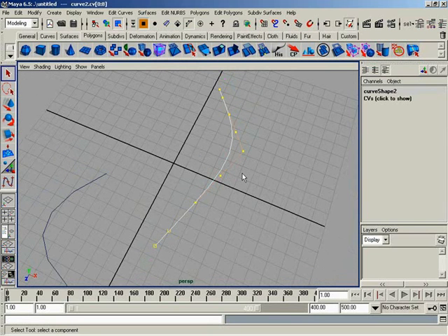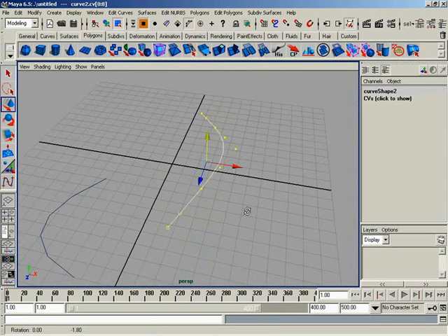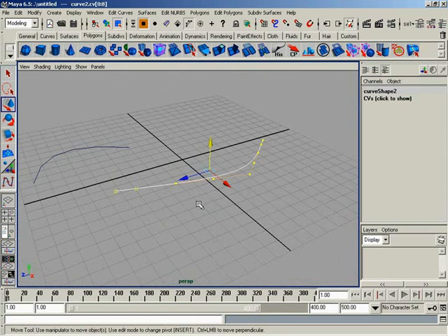Holes are very important when modeling, and you need to grab a consecutive row of CVs. You can simply turn on holes, grab that hole, and you have all of the CVs. Of course, I still have the ability to go in and grab the CVs on an individual basis. A hole is not something that you can manipulate per se. Again, once you select a hole, you're really doing nothing more than selecting all of the CVs. Just grab my move tool, start moving these around, and you can see that's all I'm doing, moving the CVs. Not super handy when dealing with curves, but very handy when you start working with NURBS surfaces.